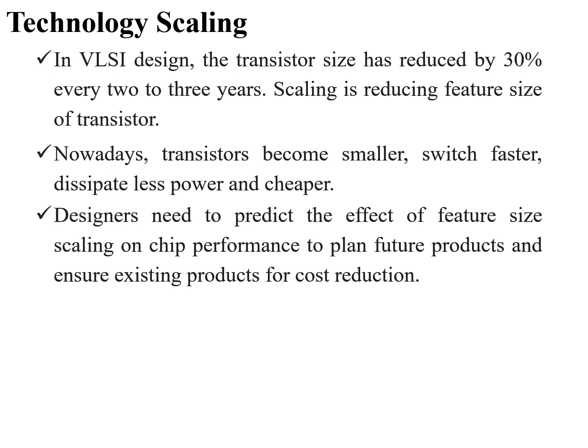Technology scaling. In VLSI design, the transistor size has reduced by 30% every 2 to 3 years, and scaling is the concept of reducing the feature size of the transistors. Nowadays, transistors are becoming much smaller, and at the same time their switching speed is increasing, they are getting cheaper, and they have lesser power dissipation. Designers need to predict the effect of feature size scaling on chip performance to plan future products and ensure existing products get a reduction in cost.